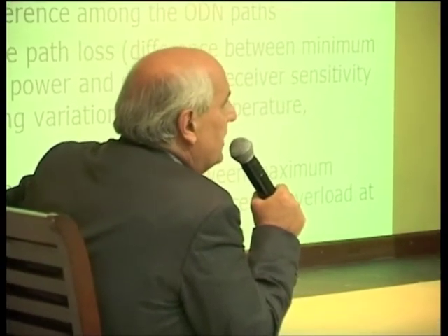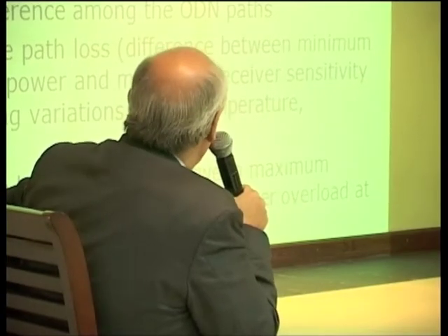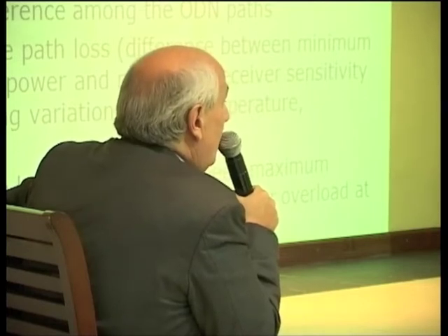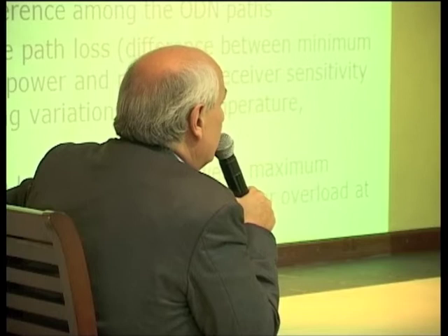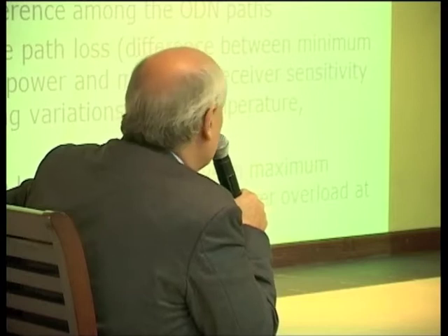How to design an optical distribution network? Well, the maximum allowable loss between the points S and R are given in the relevant recommendation. So I know that for a specific plant, I have, for example, 10 dB or 20 dB or 30 dB to be spent. This optical loss budget includes everything in the plant, which means fiber, splices, splitters.